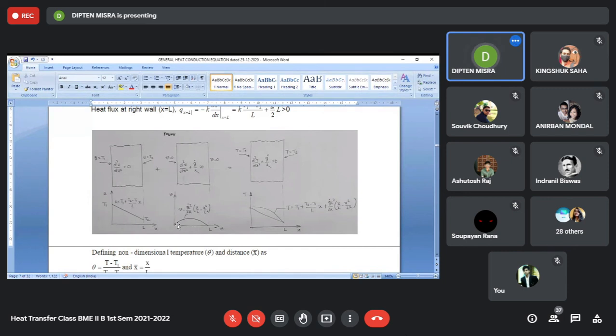Now here, the temperature gradient is negative all through, whereas here on the left hand side, the gradient is positive because heat has to be pumped out. Because when you generate heat internally, it has to be pumped out. Okay, now how do you pump out the heat?